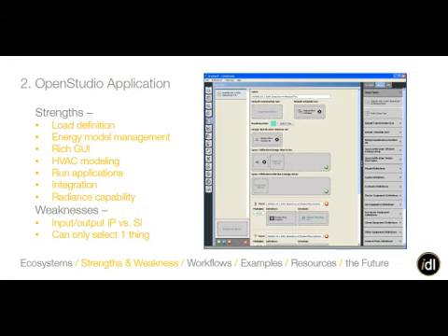And it's really a much better interface than what we saw in the Sketchup plugin. So in general, this is a space type, so you've got these different tabs that are all the major parts of the model: schedules, construction, space types, thermal zones, stuff like that. You've got an object menu here. This is a specific space type, so this is all the details of the space type, including the loads that are in it, the outdoor air object and stuff like that.